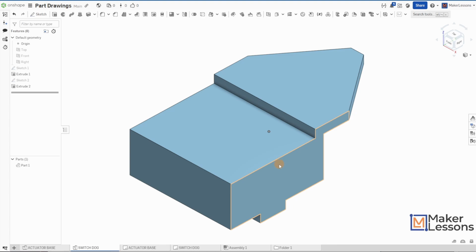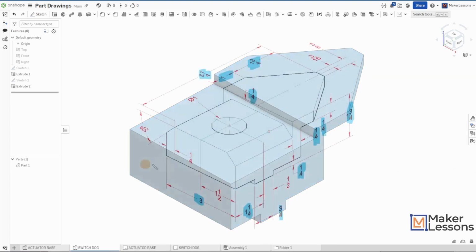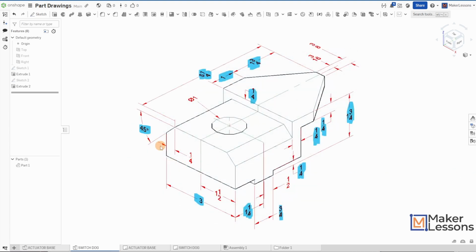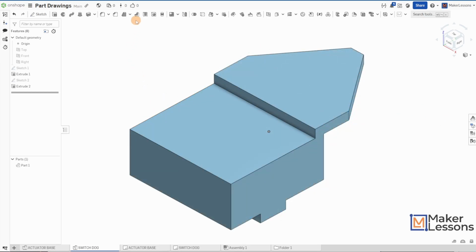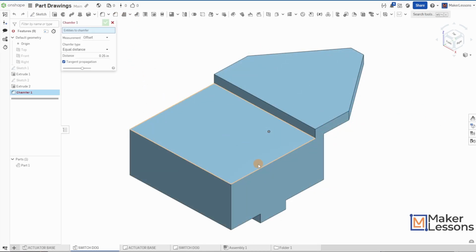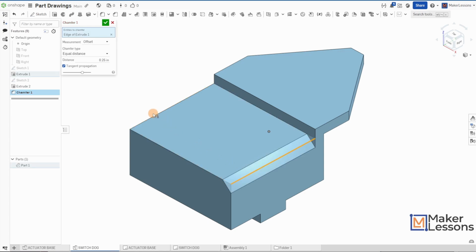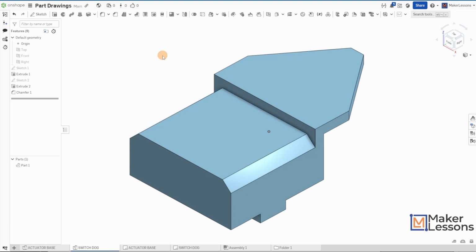All right, let's get this chamfer on the side, it's called. Looking over here, it's a 45, which is just a standard chamfer, and it's over 1/4 of an inch. So I hit the chamfer button. I click on this edge. I click on that edge. It's set already to 45, and there's that 0.25. It's almost like I drew this before, but you should add, obviously, your distance, 0.25. Check mark. Wow. We're almost done.